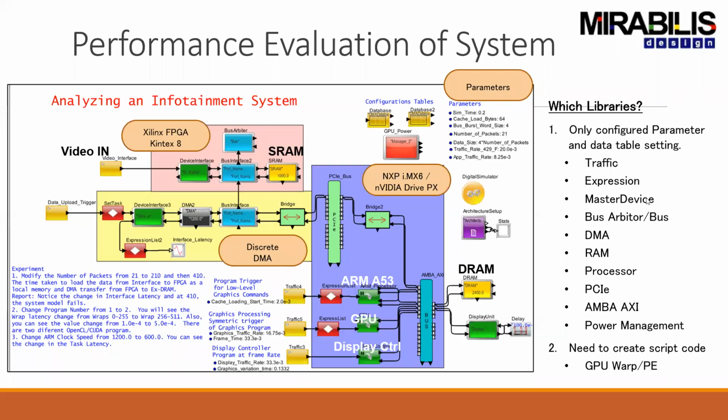And of course, a variety of components are required to make this happen. This is one particular example. It does not mean that this is the only way you can describe it, because just the fabric itself, as I mentioned, you can connect it directly to PCIe, or this does not have to be a DDR memory. It could be an SSD or a flash. So there you have a completely different type of memory controller to be evaluating. Again, this can be an AXI to a NOC to something that's more proprietary, like a lot of artificial intelligence SoCs have completely proprietary systems as well.